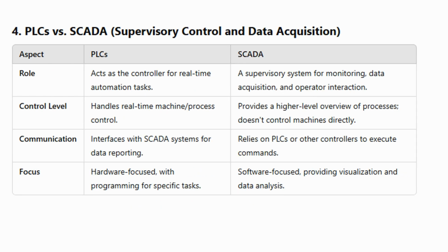SCADA: I see a lot of systems that actually combine the two together. You have a PLC and a SCADA system, a lot of times if you're doing things with a SQL database, SCADA systems can be really good at interfacing with that. The PLC can be concentrating on machine level tasks. The SCADA system can do a lot of supervisory work. But communication wise, SCADA systems often rely on PLCs to actually execute commands and control the actual hardware.